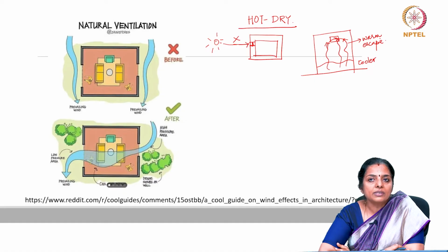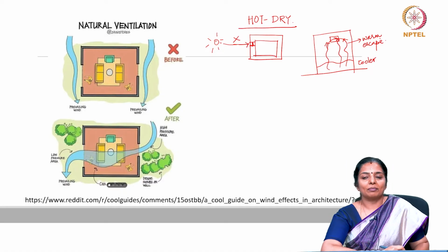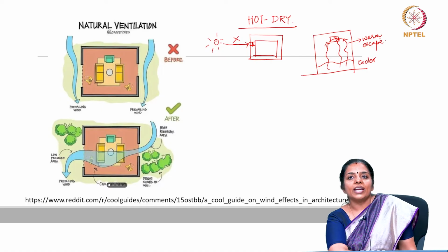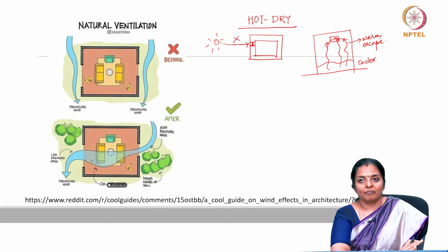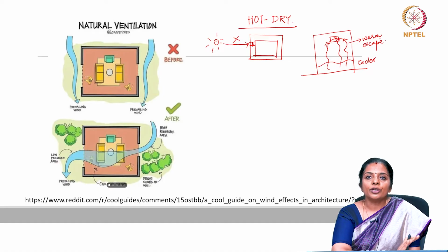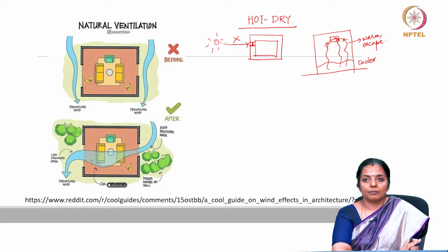In the composite zone, where all three conditions may occur, which is very complex, window shading holds the key. The shades must cut off summer sun but permit winter heat gain. It should be controllable. The window area would be determined by the duration of each season. If the winter or humid season is long, large windows are preferred.